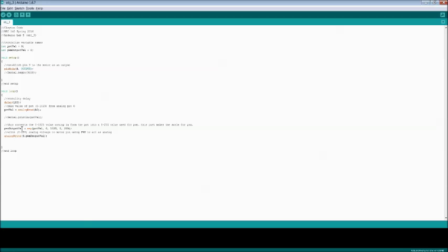Here we are declaring the PWM output value as a scale of the potentiometer value, which is on a scale of 0 to 1023. What this does is change this scale of 1023 into an evenly scaled 0 to 255, converting from the analog input to a pulse width modulation analog output, which has bigger increments, which means you have a smaller count.